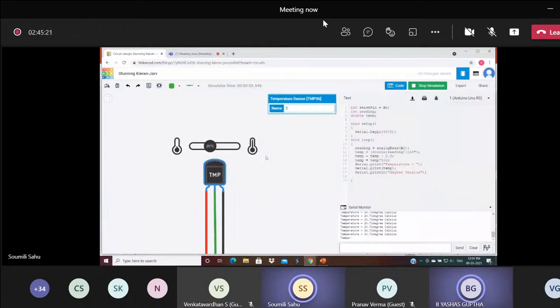Okay. Can you please show the maximum and minimum value? See, it's 125 degrees Celsius. It's printing somewhat 124.80, and this is minus 40. In Tinkercad, it's not the proper range of the temperature sensor, but it is between that.